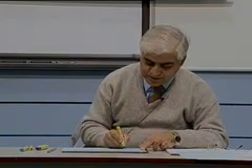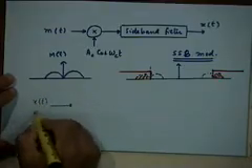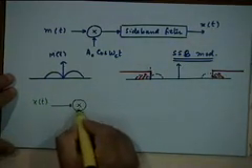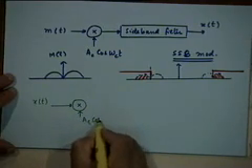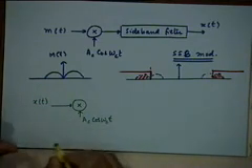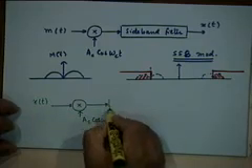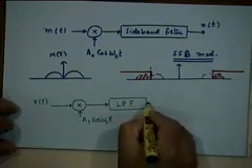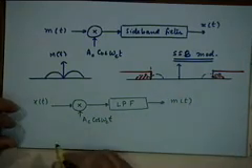Convince yourself. What I am saying is, as far as the demodulation is concerned, take your modulated signal x(t), multiply it with a coherent carrier which is in phase and frequency synchronism with the incoming carrier, and pass it through a low pass filter, and you will get your message signal back. Is that obvious?